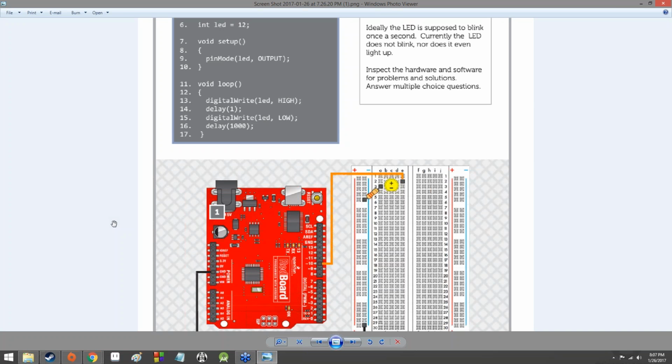You guys are definitely identifying that problem in line 6 of the code. The LED is hooked up to pin 10. However, the LED pin variable in the code is set up to be pin 12, which is a bit of a problem. That does prevent power being sent to the LED. So that's definitely the reason why it's not turning on at all. However, you might be running into very vague issues, even if you got that set up correctly. What else might be weird about this?